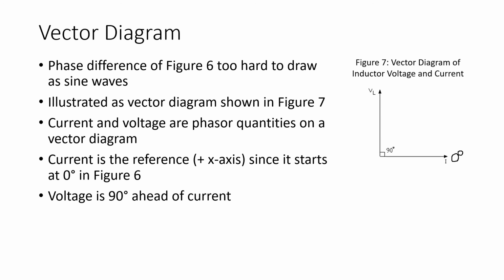And we quantify this opposition to AC current with reactance, symbolized with the letter X, and the reactance of an inductor, X sub L, is 2 pi f L. And again, inductors have two oppositions to current, the value of inductive reactance and the wire resistance. So we use the quality factor Q to quantify this relationship between inductive reactance and wire resistance.